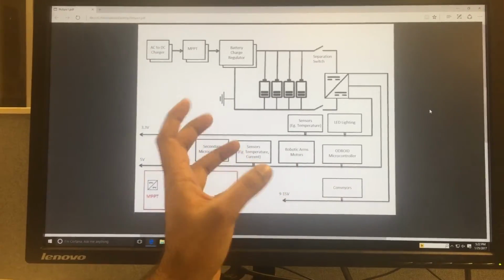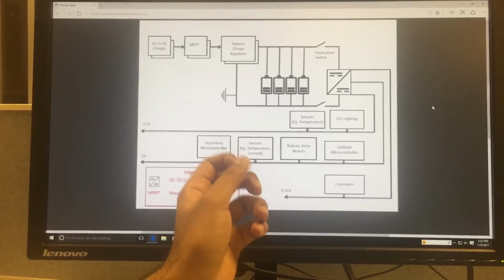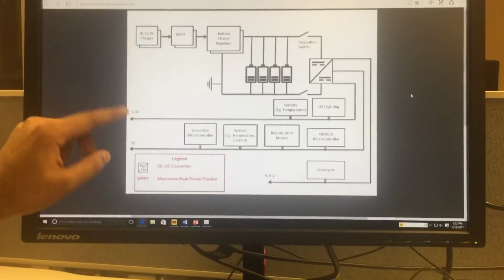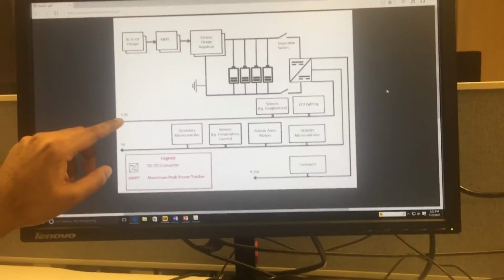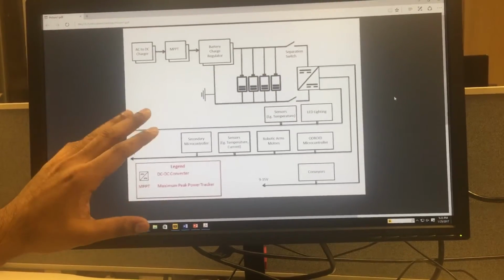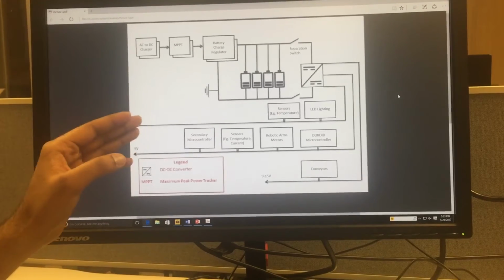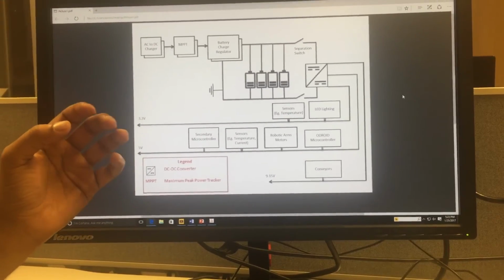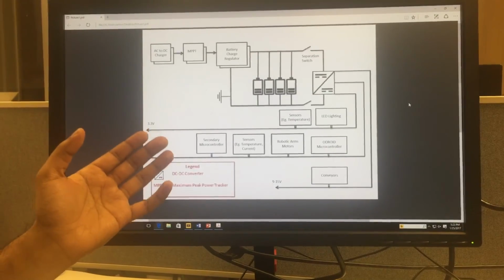In all the variations, or in case of any failures, we'll go by the differences in the voltage outputs. If it's within a 10% range, we are okay, but if it's more than that, then we'll be failing the test, and then we have to start all over again with the power tests.